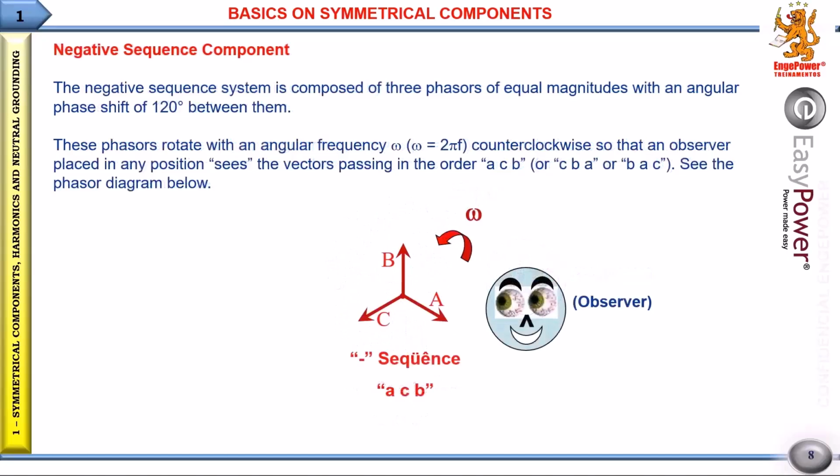He also creates the negative sequence components. For a negative sequence component, the principle is the same. The main difference is that Fortescue reversed 2 phases, B and C. All we know that for motors, if we reverse 2 phases, the motor will change the rotation direction.